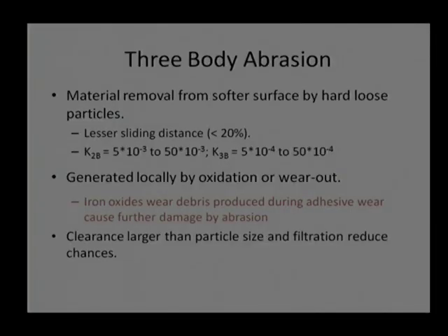Of course, if the shape is very irregular and one dimensional, then sliding will be more. But if the particle has more of a spherical shape, if you push it, there will be more and more rolling. So, for a loose particle, even though the hardness is very high, there will be overall lesser sliding distance, because there is more rolling distance, and if that is the case, wear rate will be reduced. It will be much lesser. Most of the energy is being absorbed in the rolling action.